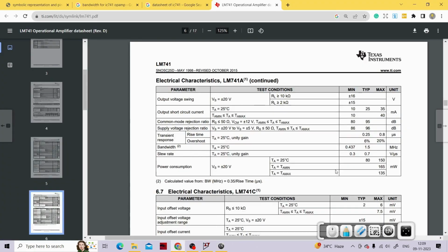So you see over here, this particular op-amp IC741. If you go with a modern day op-amp, it can withstand a 20 megahertz frequency as well. So that's the advantage we get. And that's why op-amp is designed in such a way that not only does it provide high input impedance and high gain, on top of that it also provides high bandwidth, or infinite bandwidth ideally, or high bandwidth, that means around 20 megahertz.